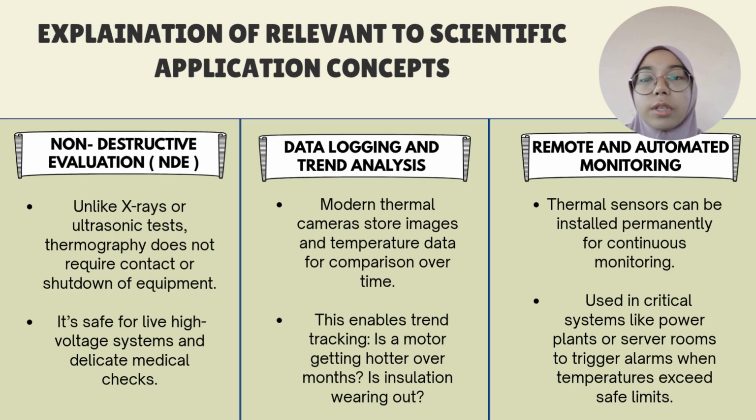Now, let's move on to the explanation of the relevance to scientific applications of the thermography concept. The first application is non-destructive evaluation (NDE). Unlike X-rays or ultrasonic tests, thermography does not require contact or shutdown of equipment, which is why it's safe for live high voltage systems and delicate medical checks.